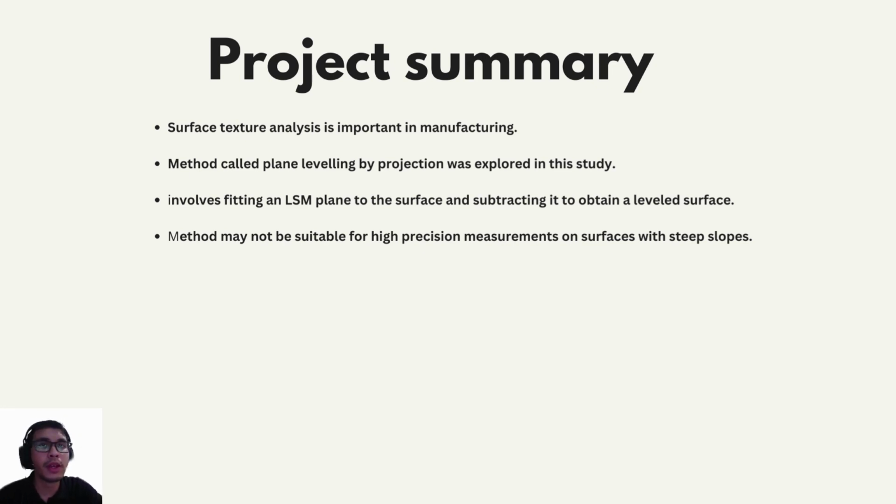There are various microfabrication processes that can produce complex 3D surface or shapes, which can be challenging to precisely measure using traditional methods. In this study, we explore an alternative method for leveling surface topography data by using surface topography feature as a reference. Plane leveling by projection is a technique often used in surface metrology to address discrepancy between the surface of a specimen and the measurement plane on the instrument in the x and y direction.